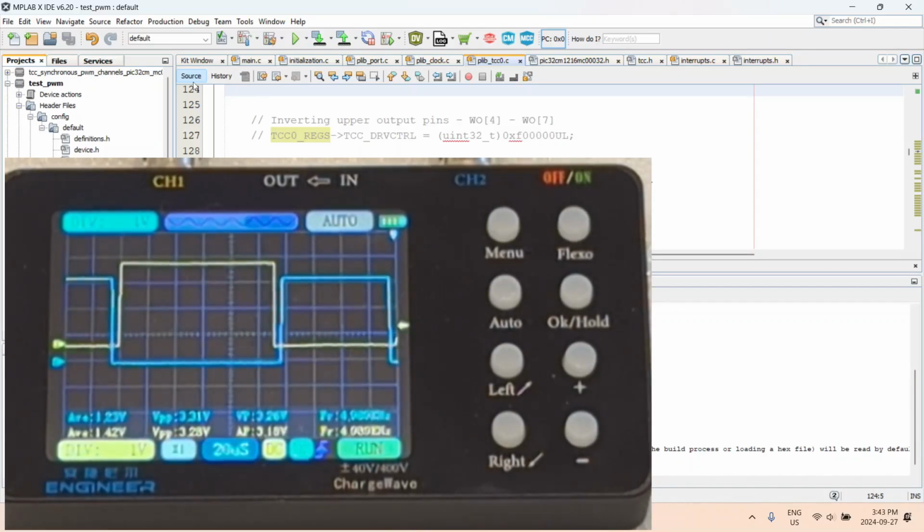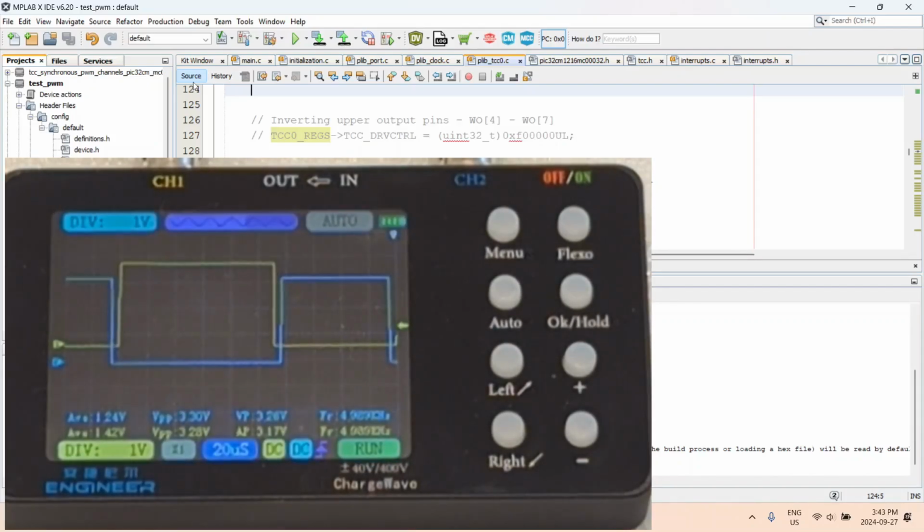So if you got these results, we have now been able to produce a practical PWM gating pulse which we can feed to an actual converter. Because remember, now not only are we able to set the frequency, we are able to set the modulation signal, we are also able to vary the pulse width. And last and most important, we are able to insert a dead time so that we do not short circuit our DC bus. So with this, I will end the oscilloscope video.